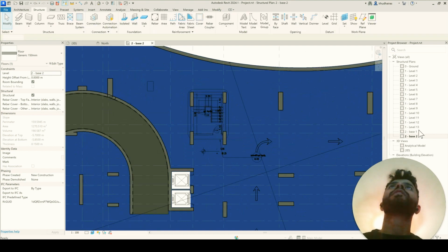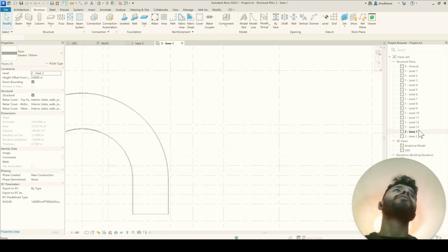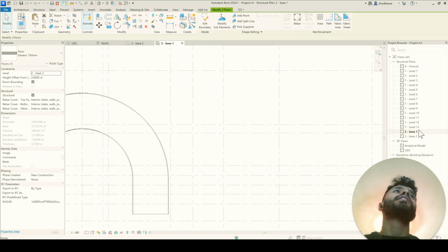So what we're going to do is move it to a different floor, then arrange the starting point and the finish point for the stairs. It's just drawing, but say you draw something on the second floor by mistake, but it should be on the first floor. You just change the bottom and top level for that drawing.